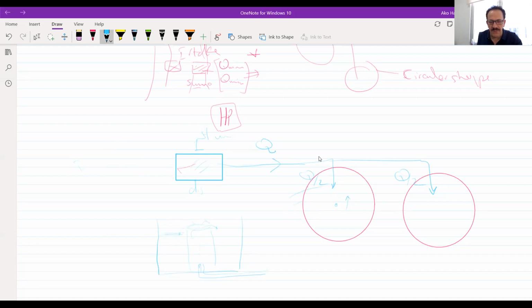It will stay for a period of 8 hours or less. If we have particles in this tank, such as sand, they will settle down until all the settling is collected here. The top part is the clear zone, or clean water zone, and it will be collected here.